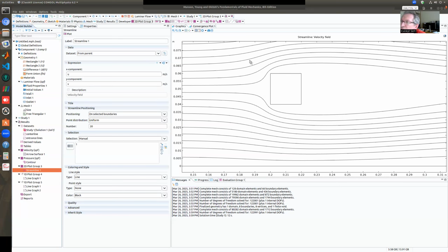We were studying boundary layers, boundary layer separation and such things. We haven't studied the separation thing yet, but this flow is separated. It is not possible for the streamlines to continue along this edge and then come back and totally fill this back part. No, it's not possible. With these very sharp corners, it's just not possible. And right at the leading two corners, we have flow separation. And we have flow here, but we cannot see it in these default settings.